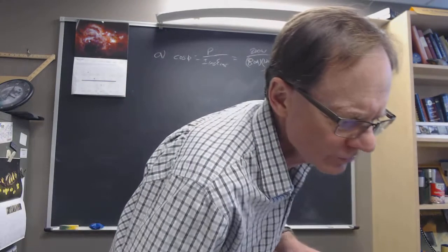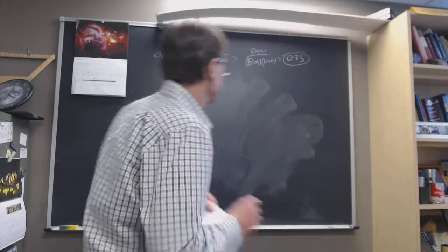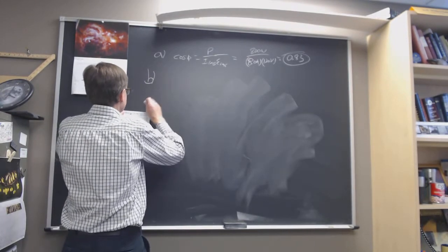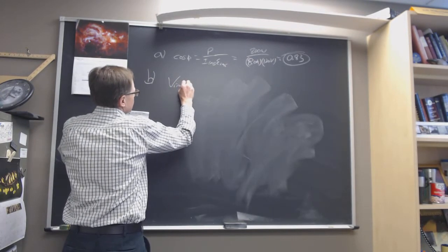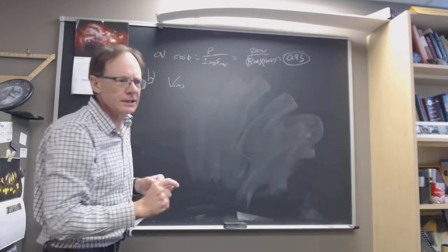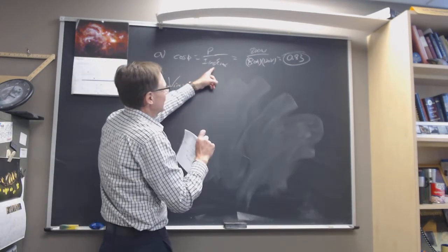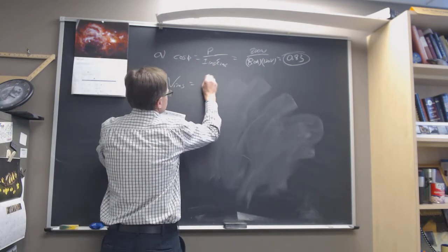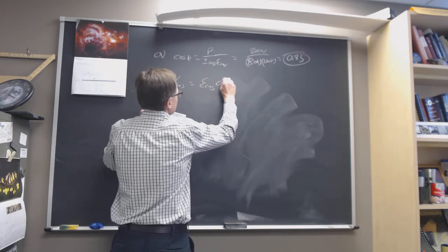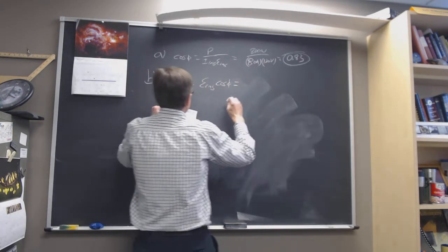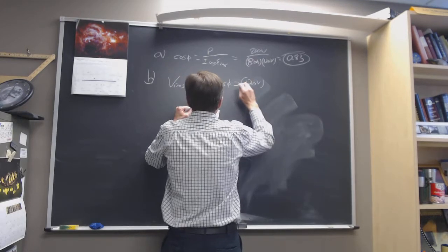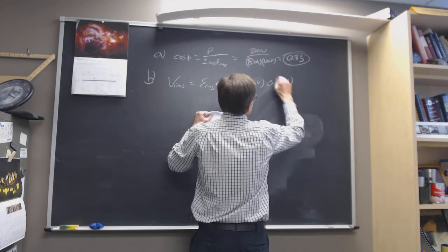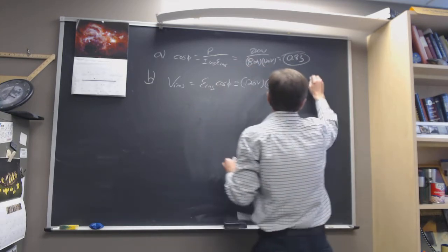Part B asks us what is the RMS resistor voltage. So for part B, we want to look at the potential drop across the resistor, which is related to the driver EMF via this power factor. So this is E RMS cosine of phi, which is going to be equal to 120 volts times 0.833. That was the extra digit that was up there, a 3, and that's going to be 100 volts.